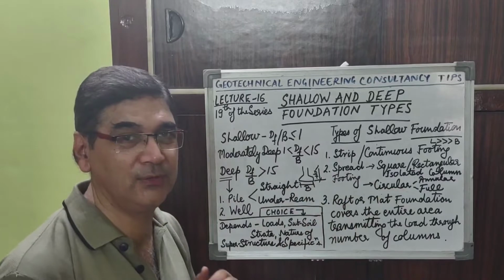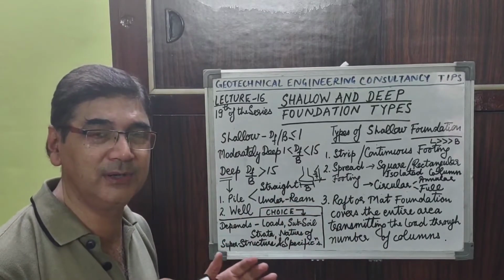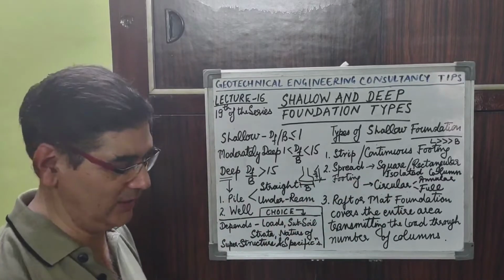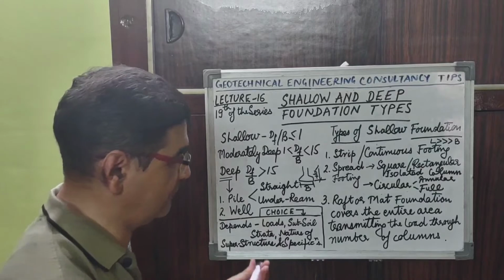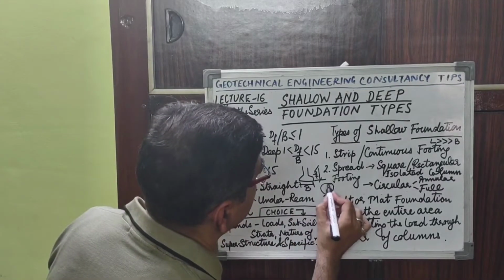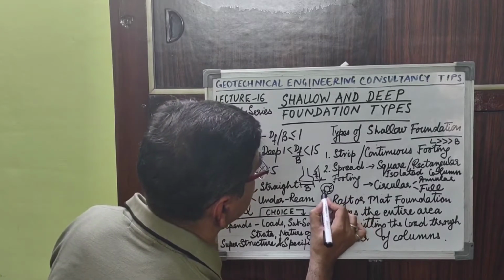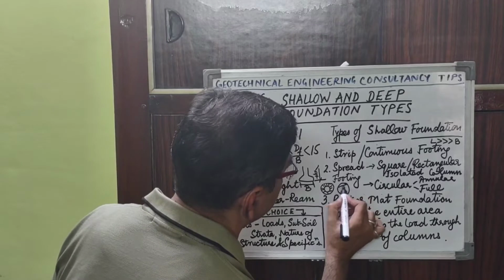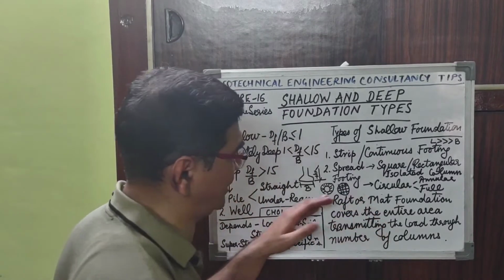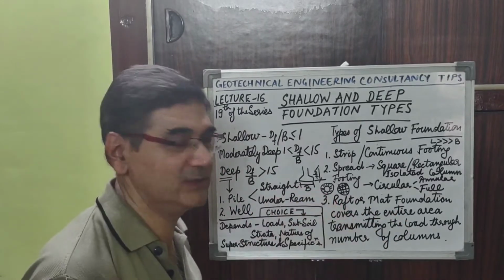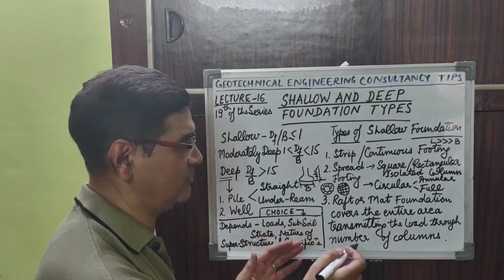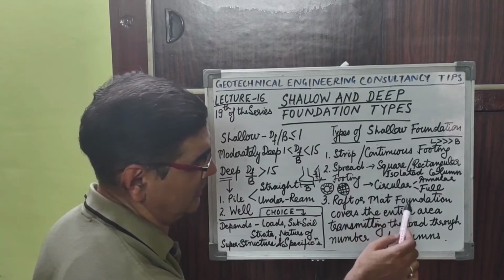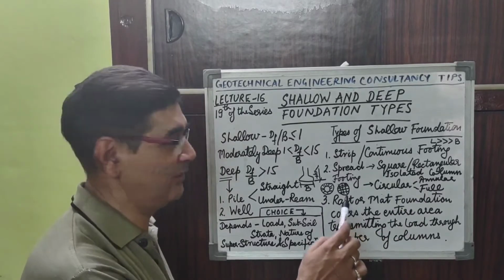And what are the kinds of circular foundations? These are of the ring or shell type. In most overhead tank cases, this circular foundation can be annular or raft. How do you differentiate between annular and raft? In annular, this is the portion where the concrete and reinforcement is put in, and a raft foundation is a full raft, with reinforcement placed all throughout the bottom of the circular raft as per the structural designer concerned. So usually annular and full circular rafts are the kinds of foundations provided for overhead tanks.